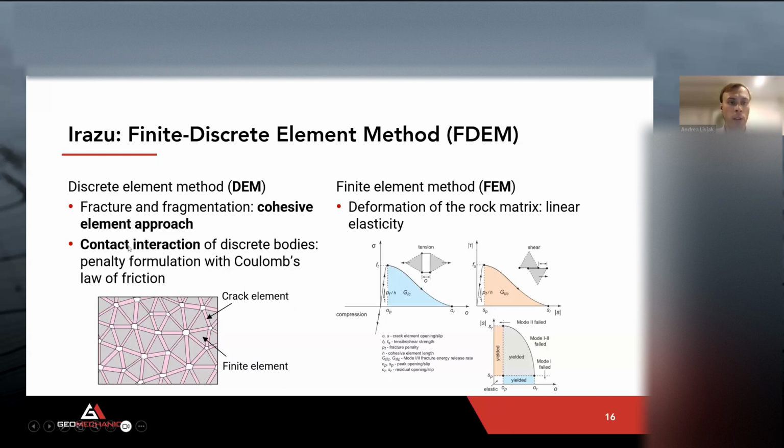The DEM part also includes the contact interaction algorithms, and these are required because either you have existing discontinuities or you form a discontinuity because of fracturing. Now you need a formulation that allows you to capture the contact between fracture surfaces and also the frictional behavior along the surfaces. This was the DEM part, and then we have the FEM part, which analyzes and captures the deformation response and also the damage response with an elastoplastic model of the solid element, so the rock matrix.